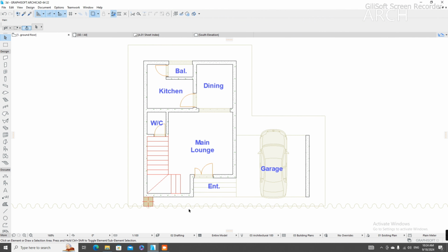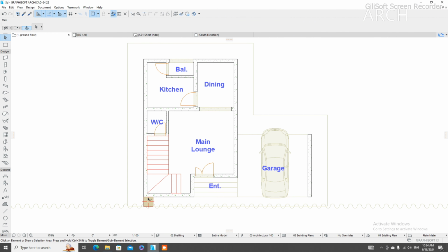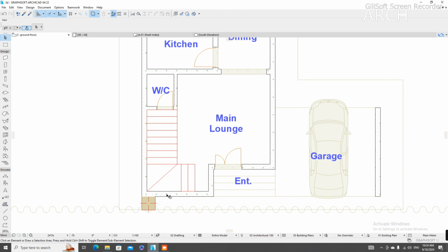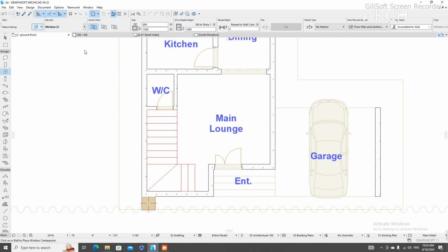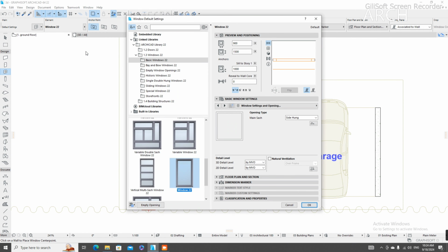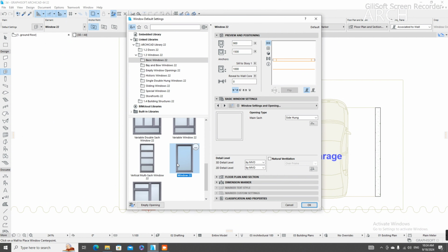Now let's go to our window. Now we need this wall to be window. So let's come back under your design tools. That's where you can get your window tools. From there you pick your window settings, and once you are done with that, you choose the window of your choice. So I'm going to use a straight wall window on this, and I'm going to take a height of, we have 360 plus 360. What's the final height?